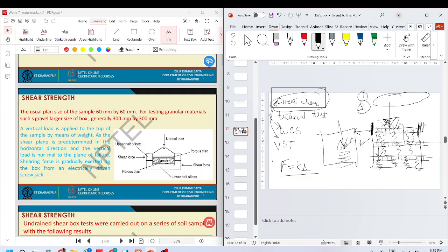So these springs will start slowly compressing, they will not instantaneously compress, and until these springs take the whole of the external load, the load is carried by the water. So here, if you had a piezometer, it would have been at this level.